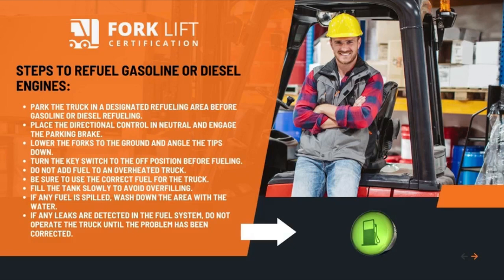Do not add fuel to an overheated truck. Be sure to use the correct fuel for the truck. Fill the tank slowly to avoid overfilling. If any fuel is spilled, wash down the area with water. If any leaks are detected in the fuel system, do not operate the truck until the problem has been corrected.